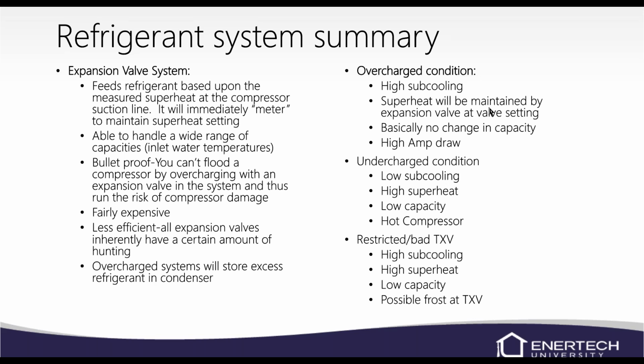Your superheat's going to be maintained by the valve, and you're going to have really no change in capacity, but you will have compressor high amp draws. You can actually hear that compressor once you get over about 400 PSI. You can really start to hear that compressor work a lot harder, and it'll just have kind of a different sound.